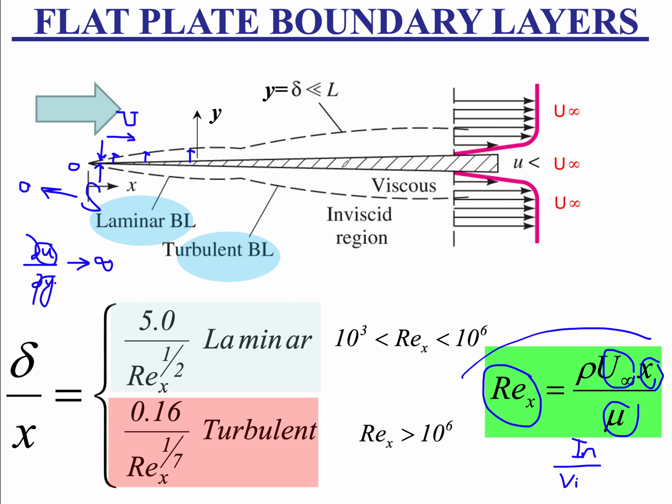As you move further and further, the effect of viscosity becomes weaker and weaker, and it loses to inertia. Now inertia takes over and the flow becomes turbulent in this region, onward from the critical Reynolds number. So this is primarily the story that we would like to at least vouch for in boundary layer theory. This is a simplistic view of it, but it's a realistic one.